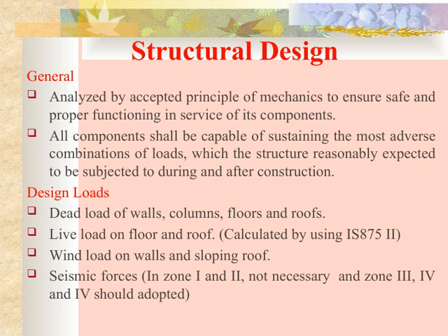And finally, seismic forces come into play, but their application depends on the seismic zone. For zones I and II, sometimes seismic forces are considered less critical, but for zones III, IV, and V, it's essential to adopt seismic design considerations. All these factors combined help us ensure that the structure remains safe, stable, and durable throughout its use.